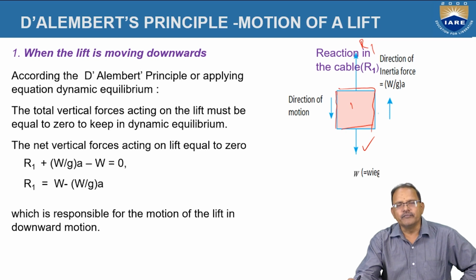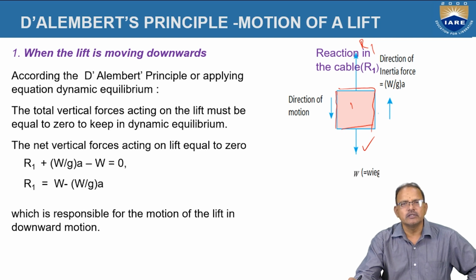Since the lift is accelerating downward, the inertia force, equal to minus MA, acts in the upward direction, opposite to the direction in which the acceleration is acting.